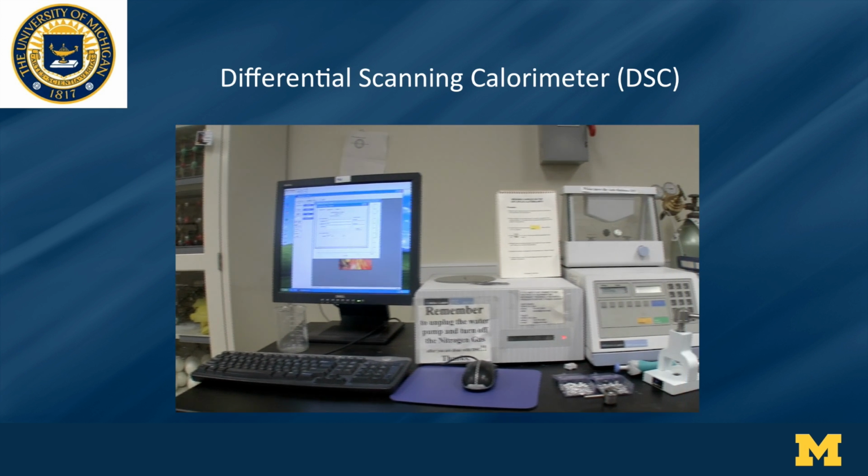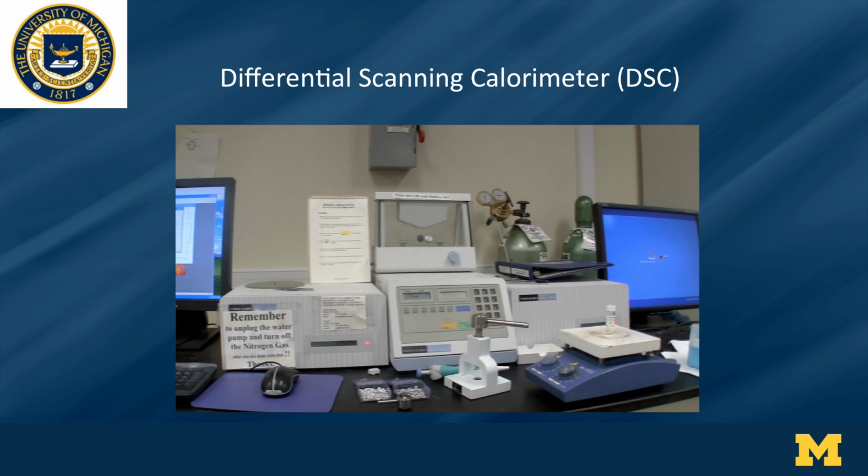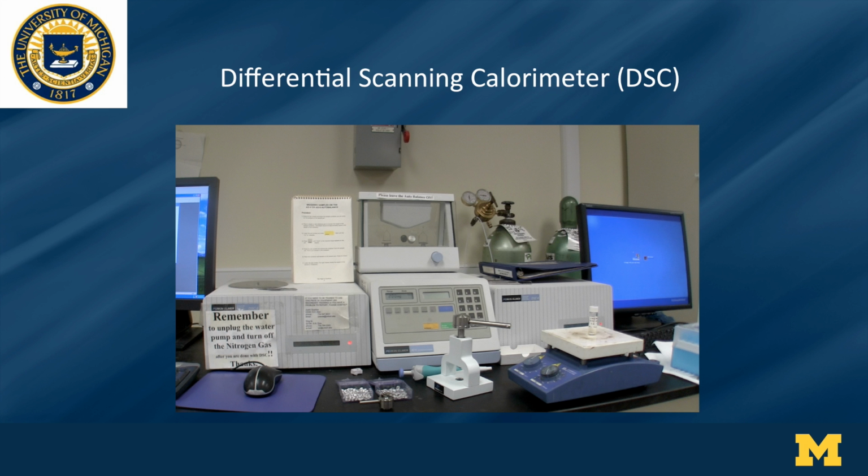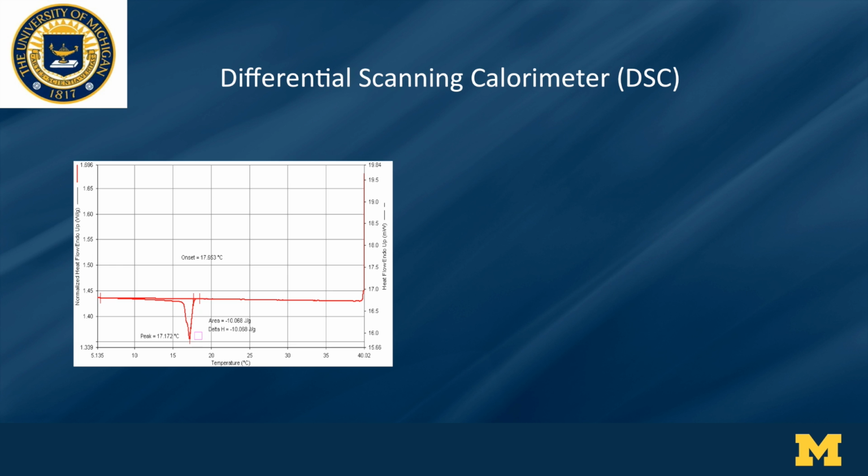In the industrial practice, DSC, differential scanning calorimeter, is often used to measure wax precipitation curve. DSC can automatically generate a heat flow curve for the testing oil sample. The cumulative heat release during wax precipitation process can be measured by integrating the enclosed area of thermogram and the baseline in DSC. To get wax precipitation curve, the amount of wax precipitated is equal to the cumulative heat released divided by the heat of crystallization.